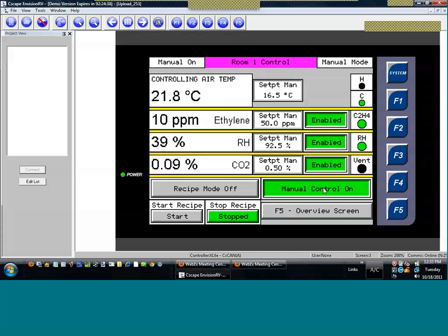We want to make sure that the fans are actually running before we start cooling or heating. And there is a selector switch in the front of the control panel that needs to be in the on position to power up the fans. Then through an off contact on that fan contactor or overload, we verify that it's actually pulled into a digital input. And if the fan switch is on and if we have our aux contact made through the digital input, then the controller knows it's okay to cool or heat. So again, this is exactly the same as at the touchscreen itself.